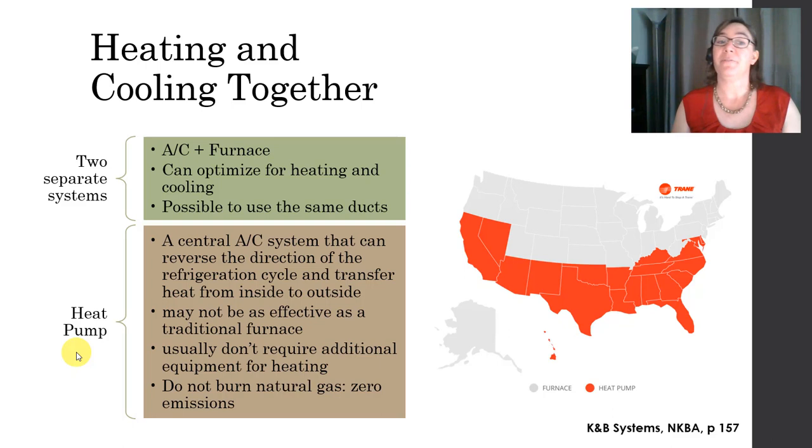It might not be as effective as a traditional furnace. And that's why you don't want to use it for areas that get really cold, okay? But the positive of a heat pump is that it does not require you to install additional heating equipment, or buy additional heating equipment. And finally, for your sustainability goals, heat pumps don't burn natural gas, and therefore they have zero emissions.